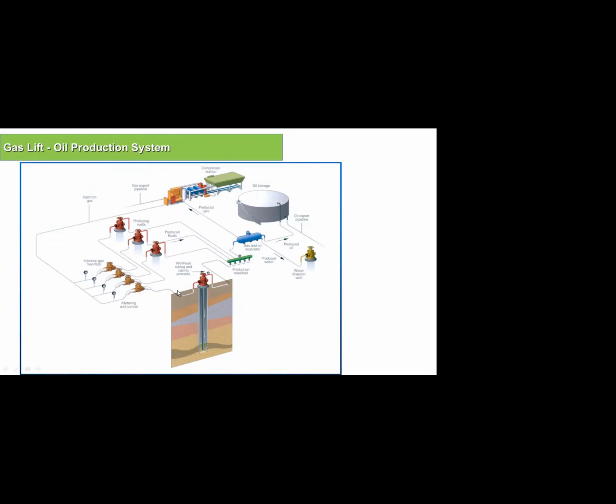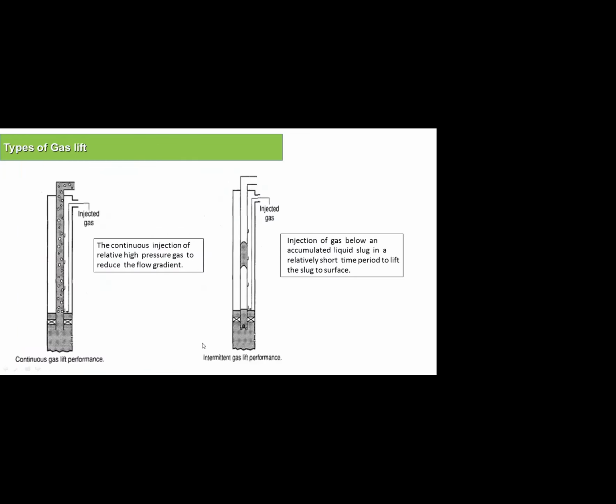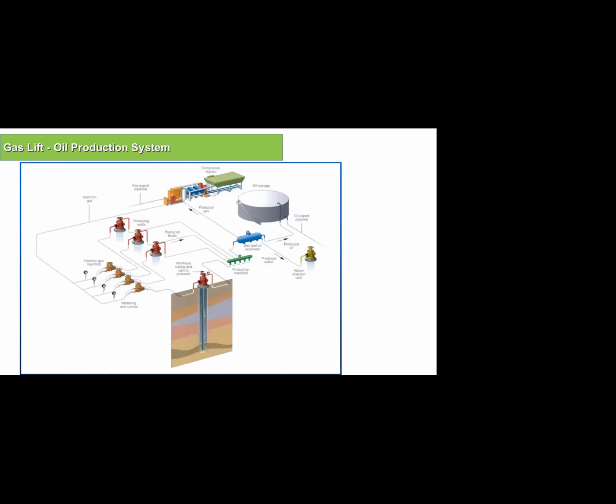And on a certain platform, we have a different injection pressure. The injection gas pressure is like 1500. So the gas is compressed here. It is filtered from hydrates and from any particles, and then it goes to the injection gas manifold, goes into the annulus, and is injected here. So now we understand why we are using gas lift, its benefits, and at the same time, what the constraint is.